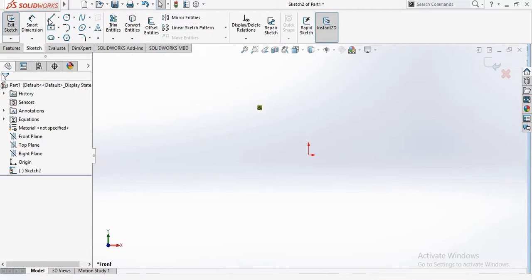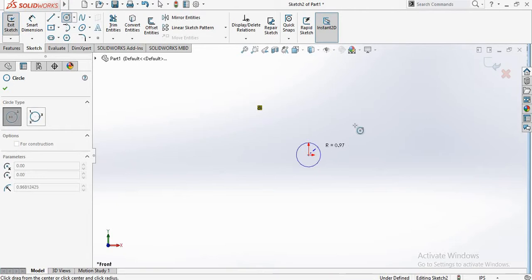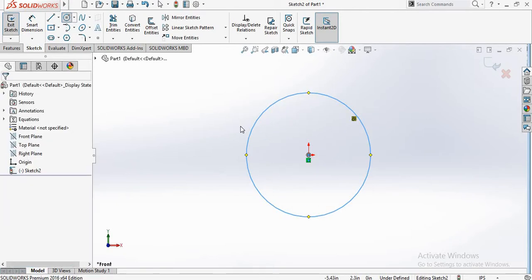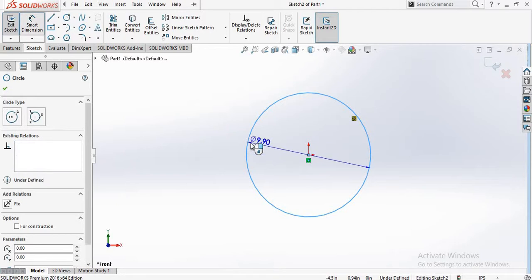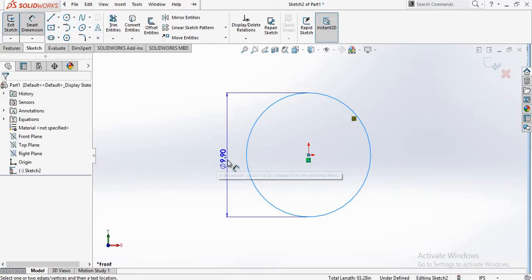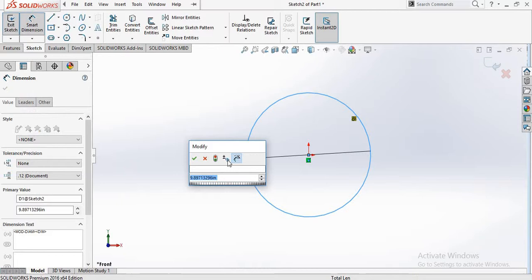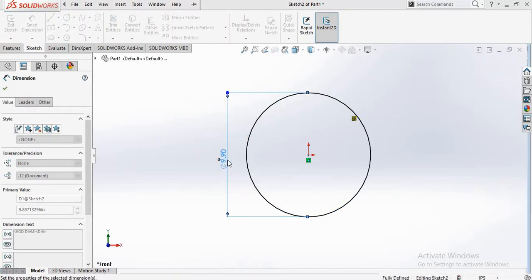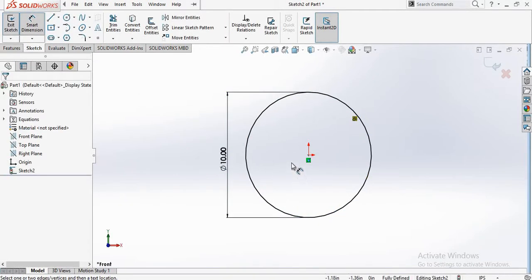So offset command, how it works: let's say you have a circle at a particular dimension of 10-inch radius, and you want to draw a circle of, let's say, 12-inch and an 8-inch radius. In order to do that, you don't have to just use the circle command instead. Although that's a pretty simple case, for actually complex geometries it becomes easy to use the offset command.